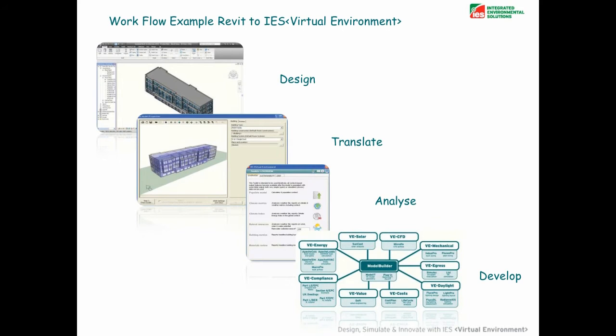So the workflow at the moment is basically the one that we would follow. You'd have your design model within Revit, and you can translate that. There are two dialogues that you can use to do this. Depending on whether you're using Revit Architecture or Revit MEP will really determine which method you use at the translation stage here.